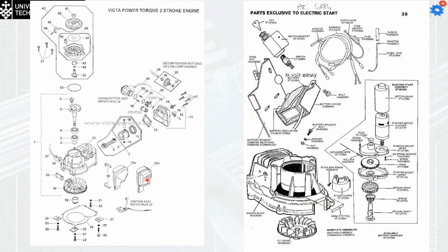So these are some of the catalogs for the full assembly of the engine and block for Vector. You can see why we need very high tolerances for these parts: the cylinder with the rings sits inside the cylinder bore, so the tolerance between the rings and the cylinder bore should be very high. Otherwise, we will have either a very tight movement between both, or a loose contact, and then some of the pressure will escape from the engine while operating, and this will reduce the efficiency by a huge amount.